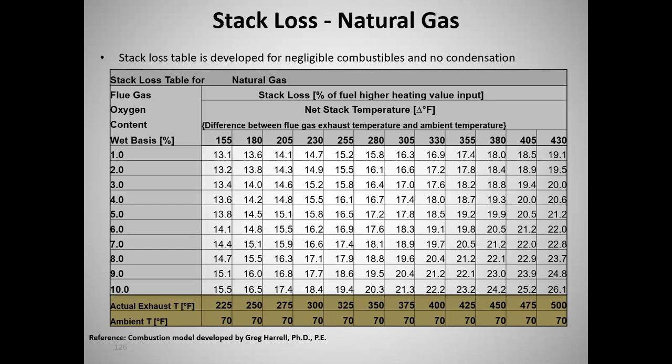For dry measurements, what they usually do is run that sample through an ice bath. They'll just put it through a line. It could actually be immersed in ice, or it could be in a refrigerated unit that just cools it down to the point that the water condenses out. Then they'll have a little centrifuge or a way to separate all the water droplets out, and then the gas comes out of that and goes into the combustion analyzer. So that's how you could take a dry measurement.